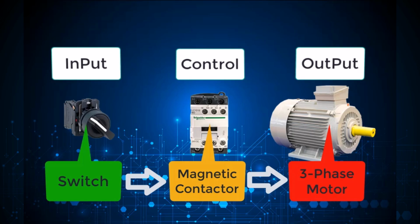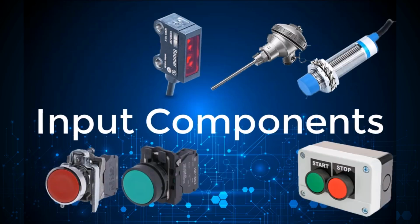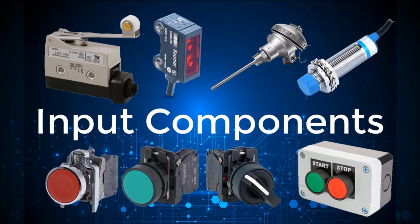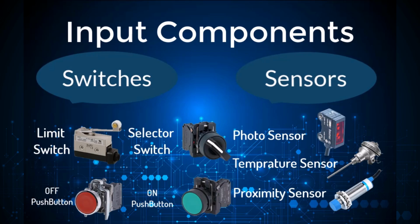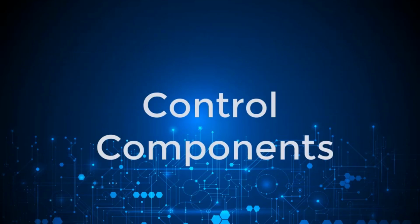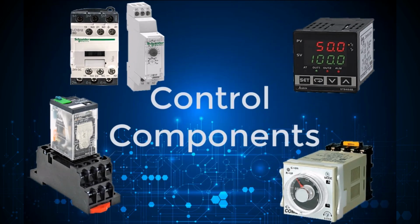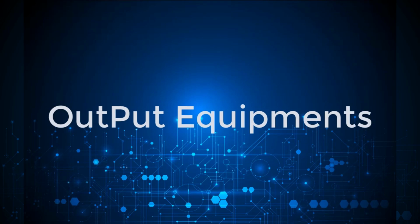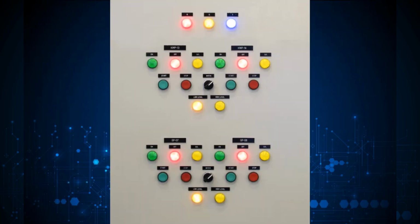All components that receive commands or instructions from the user are classified as input components. All switches and sensors fall under input components. Control equipment consists of components that process the input signals and control the outputs accordingly. This includes magnetic contactors, relays, timers, controllers. Output components are the loads that need to be controlled. These include motors, lights, heaters, actuators, etc.